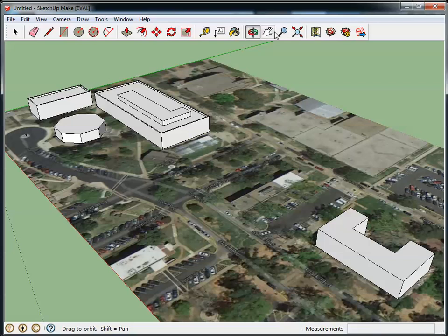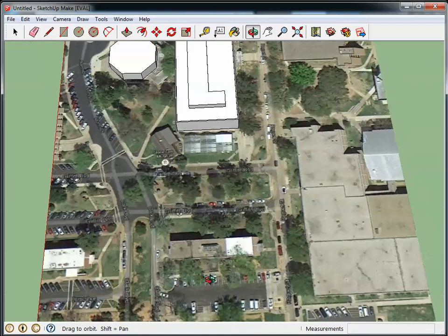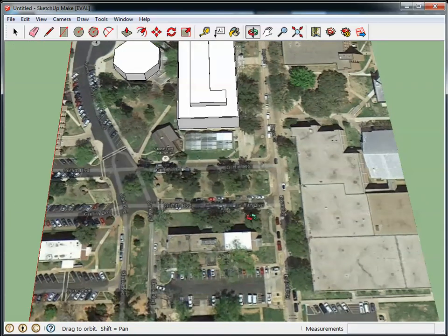If you look at the space that we're going to utilize here, this can be the parking lot right here, so we want the structure extending over that road right there and over this building here. Let's put the planetarium right up in this corner, so you can grab the circle tool and click and drag that out, click and release, and then type in 25 feet.